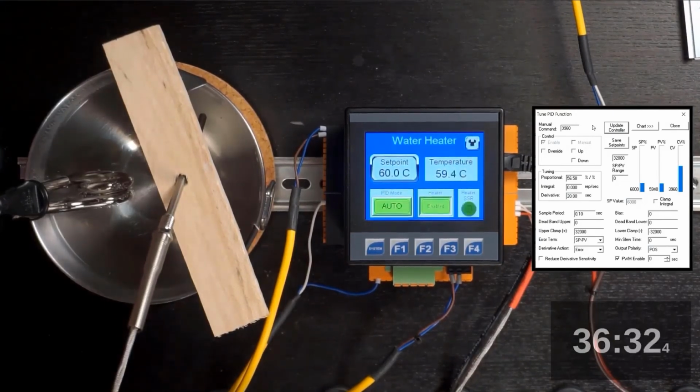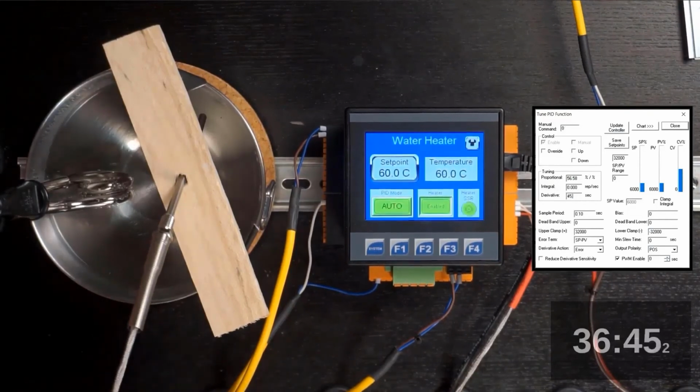I'll go back to the original coefficient value after the auto-tune, and I would imagine we'll settle back at about plus or minus 0.7. One thing to note is that I haven't played around with the proportional term at all. If I go through and do a calculation on the different proportional terms I might be interested in using, basically with the calculation I came up with, 64 was about the largest proportional term I wanted to use. So I don't think increasing it above 64 will make much of a difference. It might save a few seconds in heating the water from the beginning, but it might also have a negative impact on how tight we are for our overshoot.